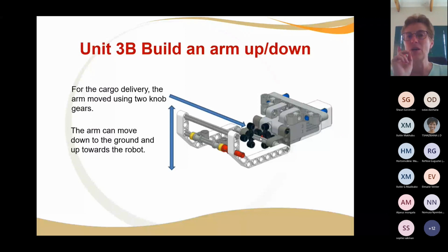All right. So just as part of some good programming, it is always a good idea, before you start, to have something that says reset arm, and then you make it come up, say for one second or 2 seconds, just to come up so that it's in the same starting position, and you know your robot is really steady. Okay, and then we can go.